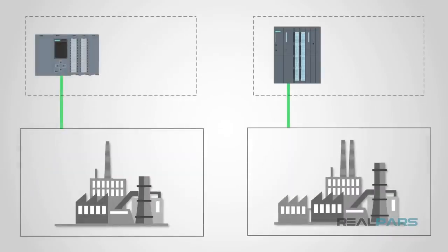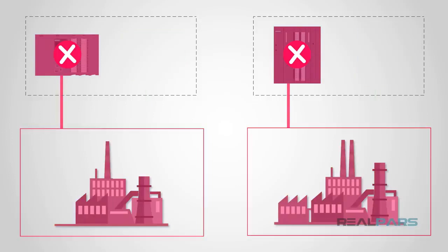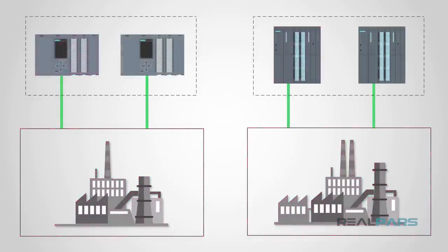There are indeed scenarios in which a PLC system would be the best option, such as smaller-sized processes, where you could employ redundant components to negate the possibility of process shutdowns. Without redundancy, you risk production halts due to the nature of a single processor controlling an entire plant. Redundancy may be deployed in either the PLC or DCS applications. We will talk more about redundancy in a future video. Just as there are circumstances for a PLC system, the use of DCS would be for larger, more complex processes that require a lot of interaction between many processors.